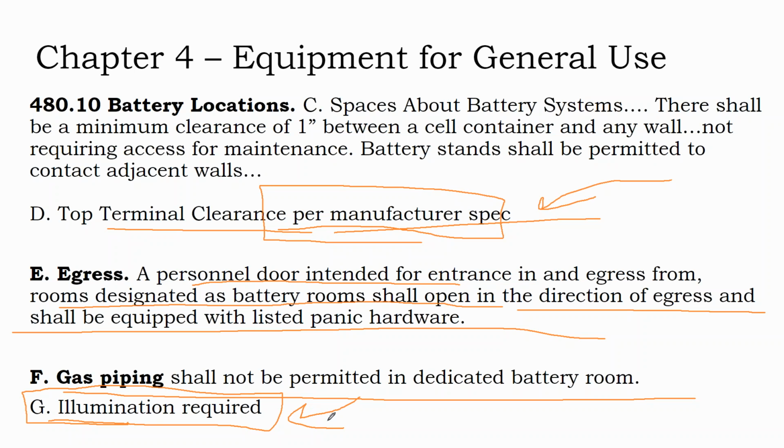And usually it's nice to have that lighting circuit be on a critical load panel coming off the battery inverter or something like that. So if something's going wrong with the system, if you still have a degree of functionality, that functionality is being spent to illuminate your working area so you can fix whatever's going on.